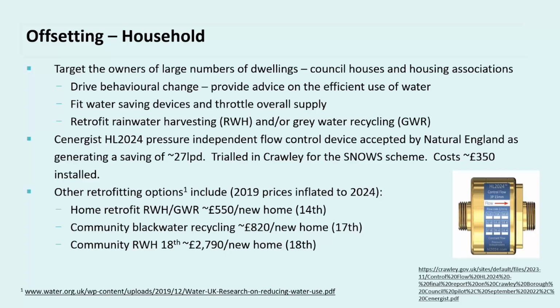And that would have a total mitigation cost of around £700 per new dwelling. Alternatively, if the example house wasn't designed with grey water recycling and just had water efficient fixtures and fittings and a PCC of 85, it would require retrofitting of just over 3 houses to achieve neutrality at a cost of around £1,000 per new dwelling. And that is cheap, believe it or not.